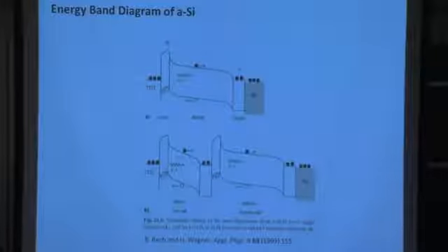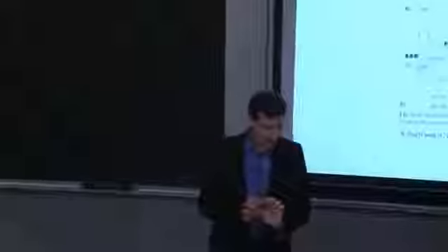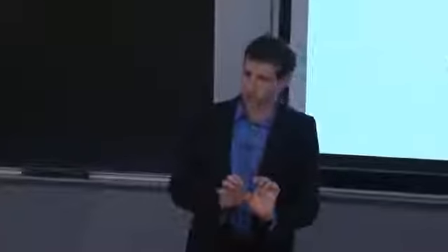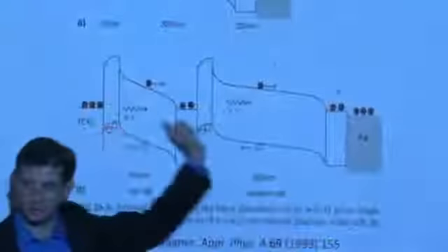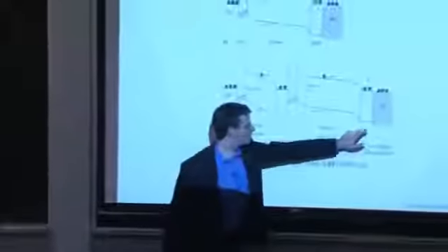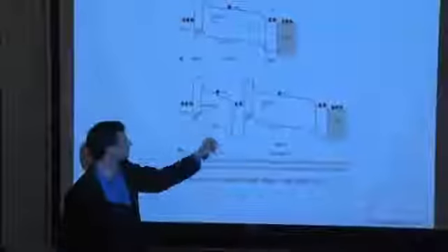If you have a two-terminal device, one can typically think about it as adding the voltages together. Then the current would be limited by the worst performer of those two. And that's why you have this layer thinner than that one over here. Because we know that the light tends to be absorbed preferentially near the front surface, we're absorbing an equivalent number of photons in this thickness and in that thickness. So the currents tend to be matched. So that's why I would guess, given the geometry, the fact that we have silver on the back and TCO on the front, and no explicit contacts here in the middle, that this is a two-terminal device as opposed to a four.